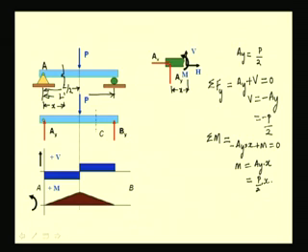So, as x increases as we move from A, the bending moment increases. At A, x equal to 0, so bending moment is 0, and as we increase x, the bending moment increases linearly. It reaches a maximum value at the mid section where x equal to L by 2, and the bending moment is PL by 4, the maximum value, and the same is plotted here.